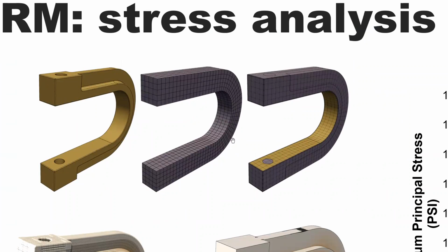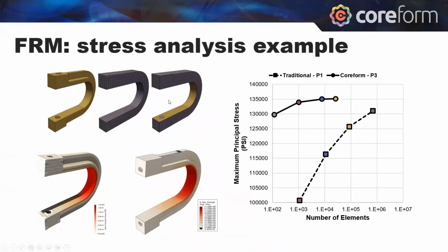we're just able to immerse it in a locally immersed mesh that's like this horseshoe that captures the main features of the model, but immerses the minor features. And then because we have U-Splines, we can build this high order basis, like a cubic, and we converge really rapidly to a solution.